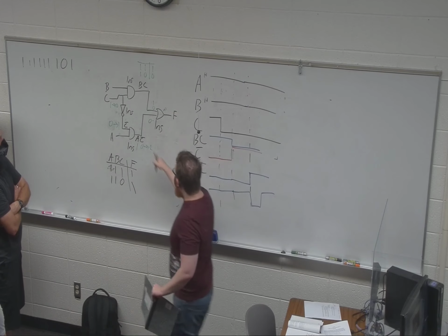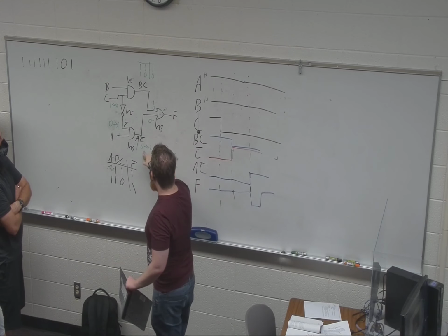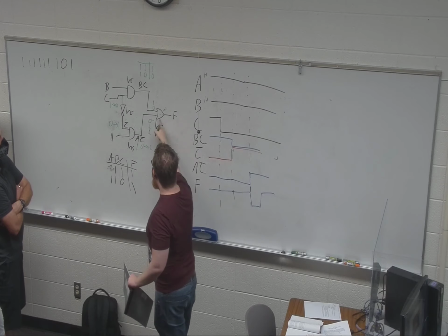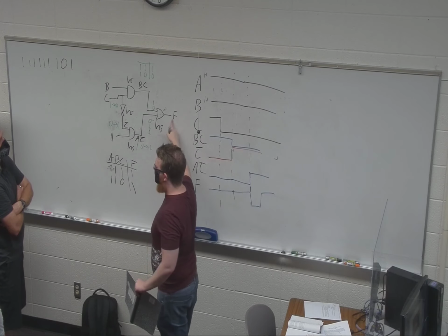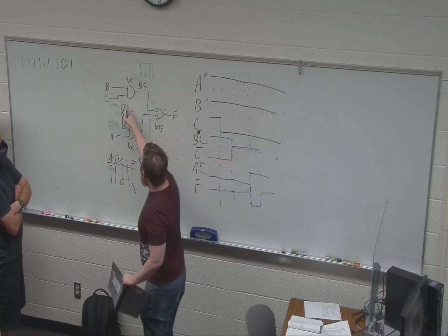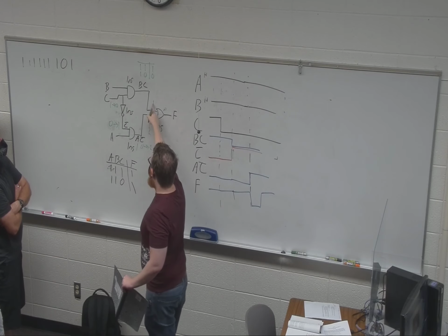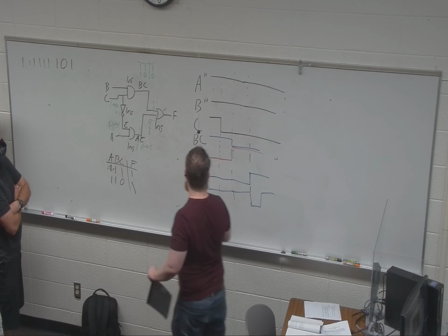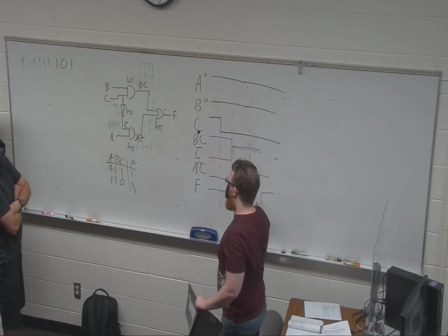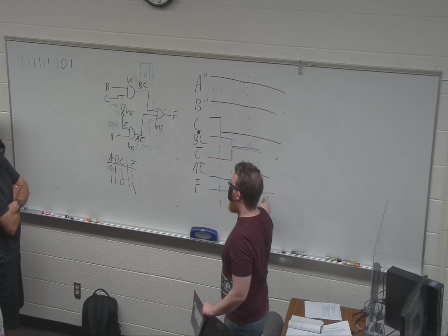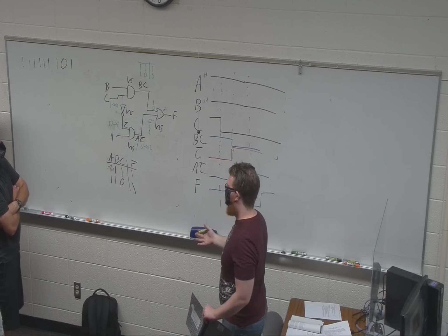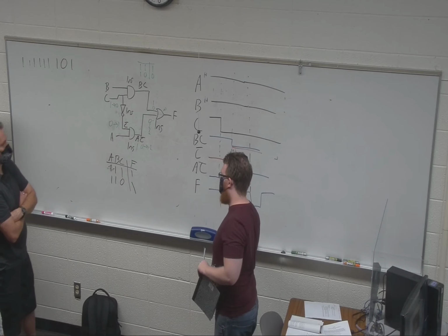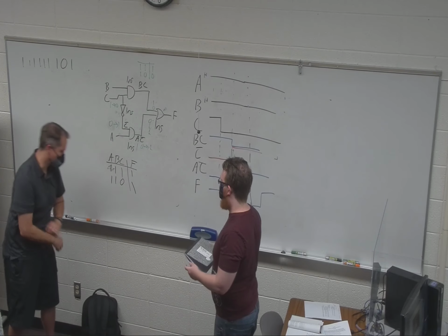Okay. So once that goes high, this guy can go, oh, look, this is now 1. That means, OR 1, I'm going to go high. But because of the delay in this route from it going, I'm no longer true, and this delay being longer saying, now I am true, you get this brief window where it hasn't seen the other branch change yet. Okay. Make sense now? Yeah. Good.